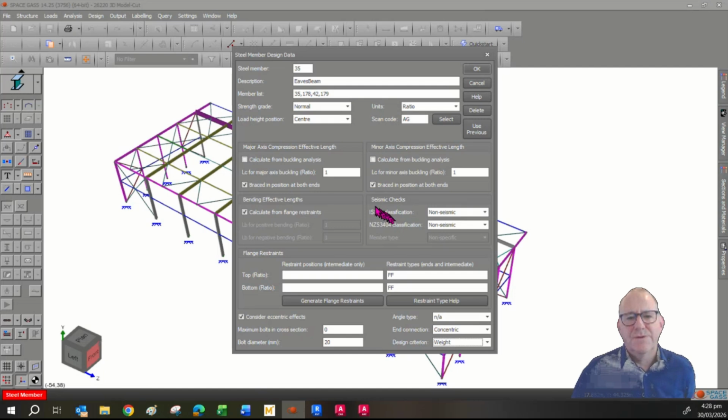So you've got to be careful that the buckling parameters you're putting in are realistic. So if you're saying it's restrained by purlins, are the purlins adequately connected to the rafters, for example, which actually apply your lateral restraint to the flange that counts. So don't forget, in a portal frame, you've got load reversal and your bottom flange could actually be in compression.